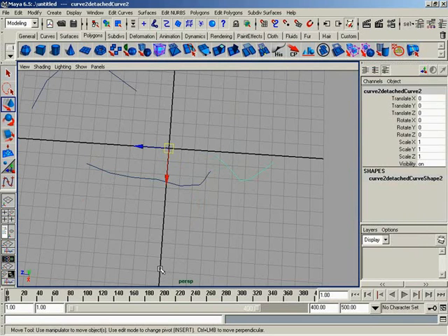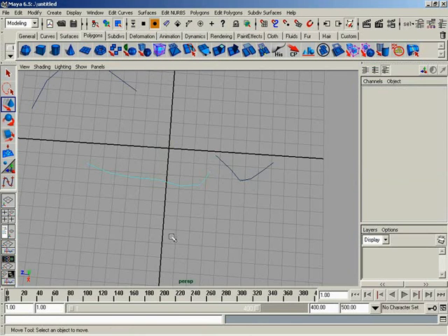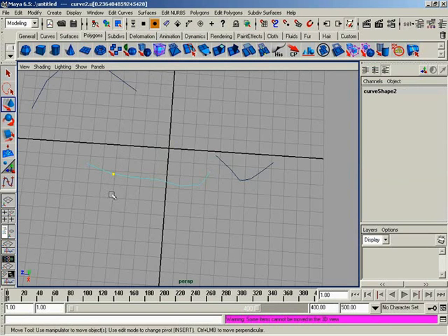And that's with holes, and curve points allow you to place a marker and even multiple markers. If I come over here and say grab my NURBS curve point, I can put one there, hold the shift key down, put one there, put one there, put one there, put one there, and now say chop this up at all of these places. It's very handy.